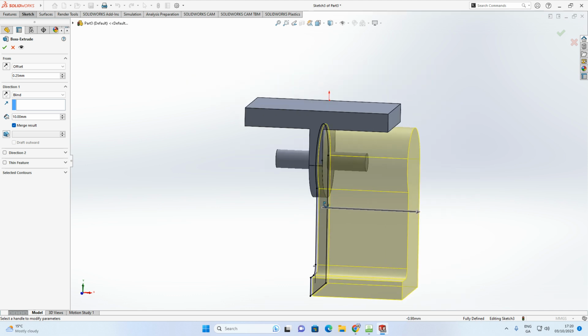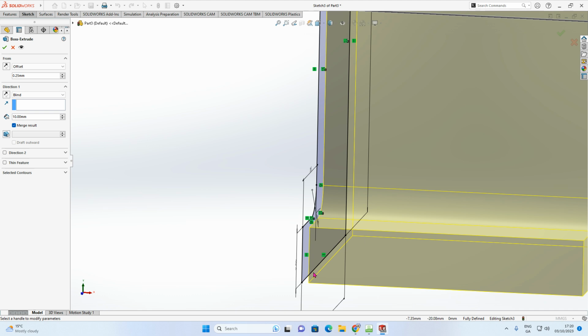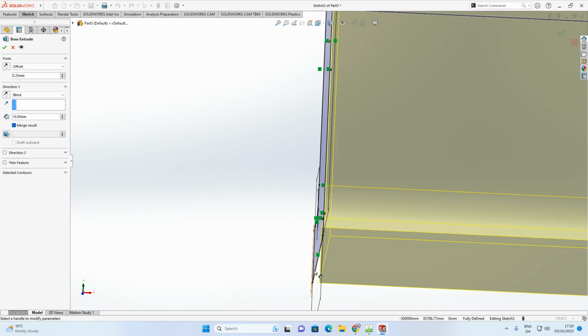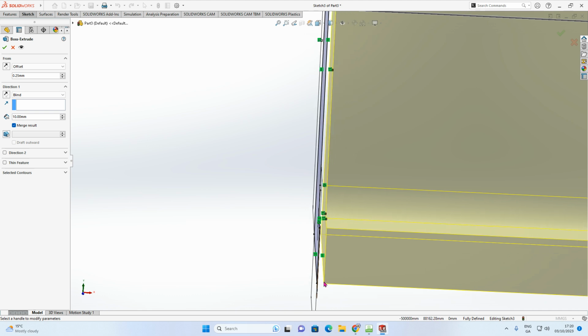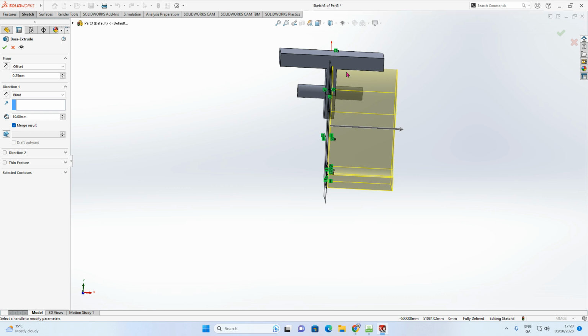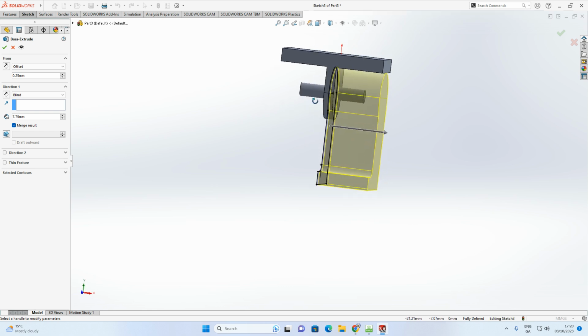Now, all that means is, it's still doing the sketch, but instead of actually doing the sketch from the surface, there's a little gap before it starts the 3D object. And that little gap is 0.25. Now, the leg is far too wide there. You can see it's too wide for the body. I only want it to be out as far as here. So based on my dimensions, I'm going to leave it at blind, but this time I'm going to change this distance of 10 to 7.75. There we go. That's matching up perfectly there.